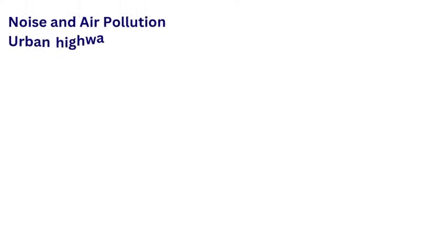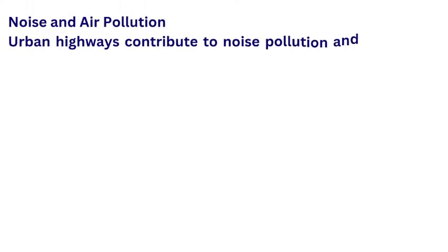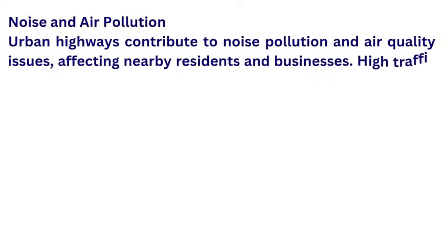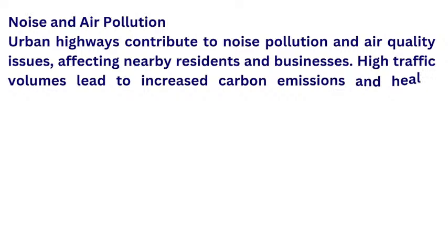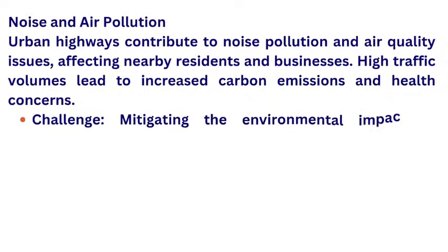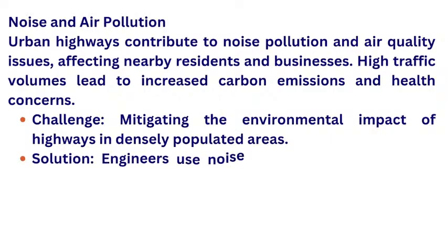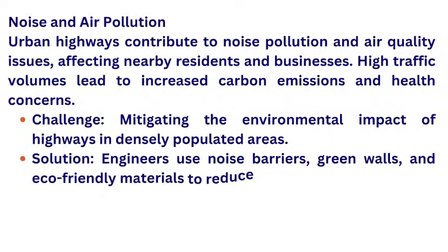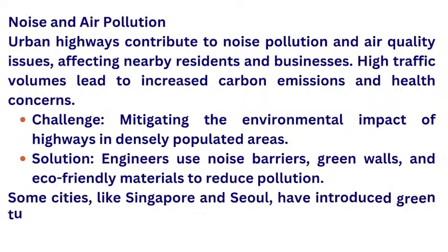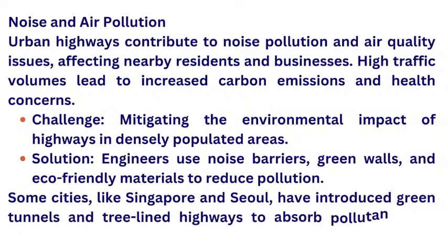Noise and air pollution. Urban highways contribute to noise pollution and air quality issues, affecting nearby residents and businesses. High traffic volumes lead to increased carbon emissions and health concerns. Challenge: mitigating the environmental impact of highways in densely populated areas. Solution: engineers use noise barriers, green walls, and eco-friendly materials to reduce pollution. Some cities, like Singapore and Seoul, have introduced green tunnels and tree-lined highways to absorb pollutants and reduce noise.